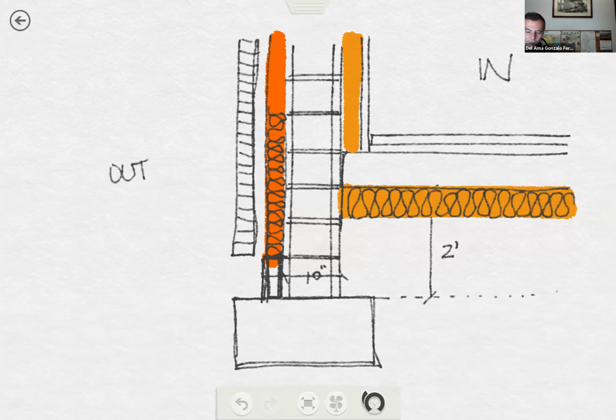It doesn't go all the way up to the footing, because thermal insulation is not a reliable material. You cannot put thermal insulation in contact with soil, water. I wouldn't do that. Okay, but I need something to hold or to bear the weight of this brick wall.